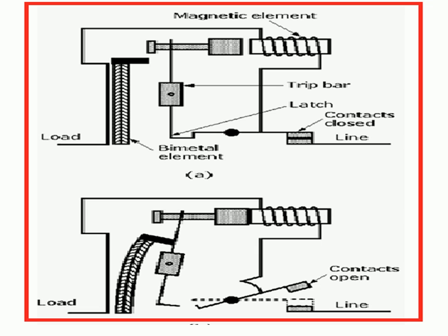This is the normal condition. The second condition we can see is when the current through the bimetal strip increases, the temperature rises. As the temperature rises, thermal expansion takes place. In figure number 2, as the thermal expansion takes place, it catches the latch point. Hence the movable contact opens from the fixed contact. The circuit becomes off. It happens when abnormal current flows. The thermal expansion of the bimetal takes place. This is one method.